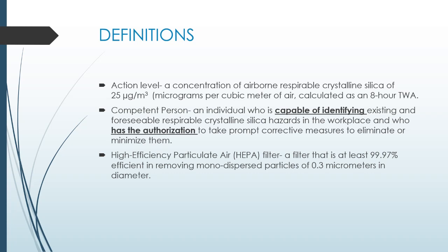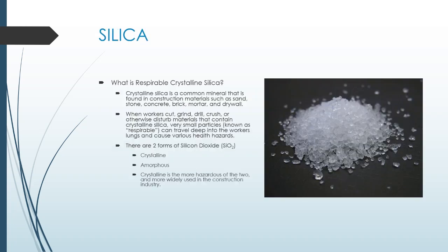When working with silica, you're going to hear the word HEPA a lot. HEPA is not a brand. HEPA is a high-efficiency particulate air filter, and it has to be 99.97% efficient in removing those particulates. That's pretty efficient. So we have to have a HEPA filter when working with silica.